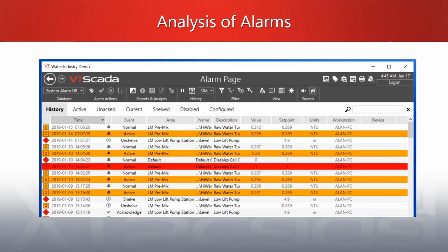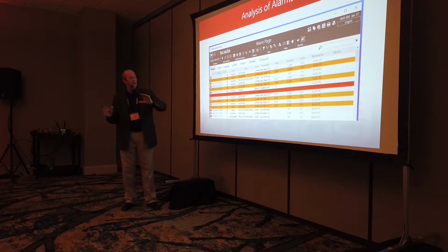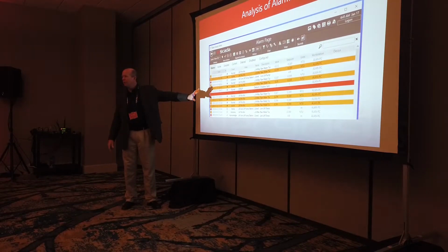Not only do you have a color for the row, you also have numbers associated with that. So here it would show, for example, a 1, 2, 3, or 4, based upon whether it's a critical, a high, a warning, or a notice. You also would have shape. So here is a square versus a diamond, and then a triangle, then an upside down triangle. All of a sudden, those become things that an operator can look at from the visual standpoint. But the bottom line is, if I'm just having a list, it doesn't do me a lot of good.